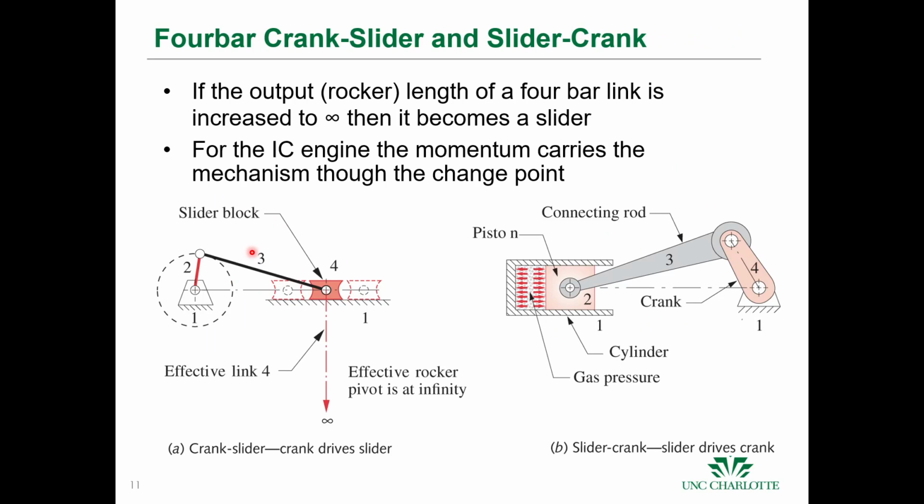In fact, if you extend the rocker arm, which is the output arm, to infinity, you just keep making that 4th link longer and longer. Well, if you make it infinite, then the grounds are still connected somehow at infinity. You still have your input crank, but in this case, the output becomes a slider.